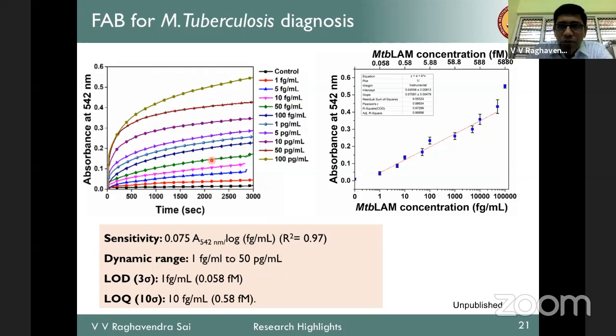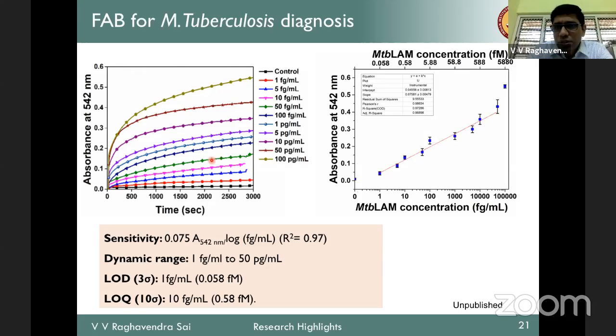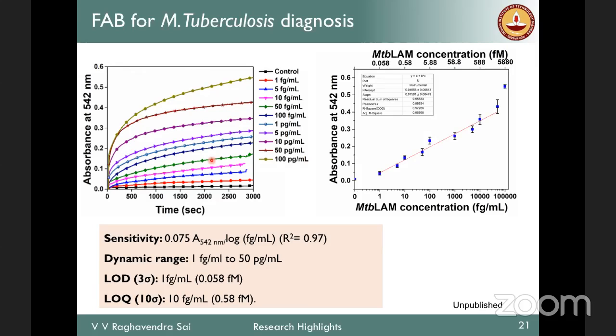LEDs nowadays have good enough optical power. You do get LEDs with 1 watt typical, or 2 watts, and that is sufficient for these applications. Of course, sometimes you just have to have a good heat sink also. But as long as you operate the LED at less than 10 milliamperes, there are no fluctuations, as we see. Okay, sir. Thank you, sir. Thanks.